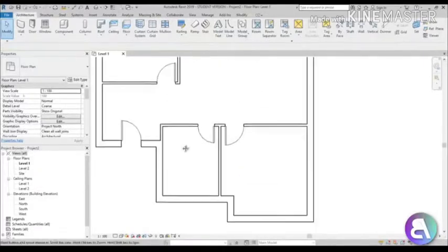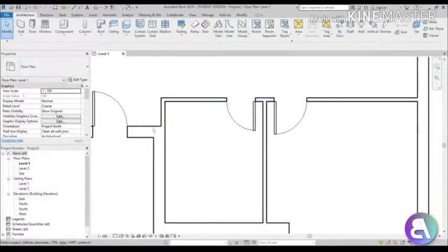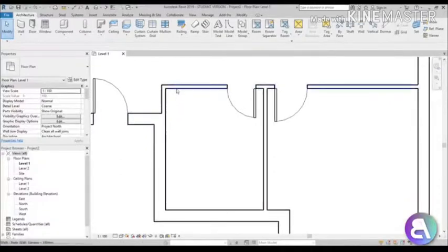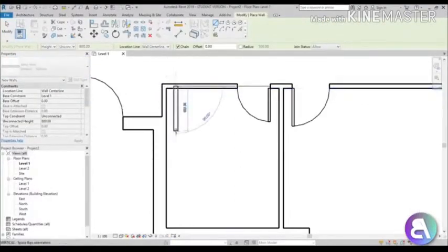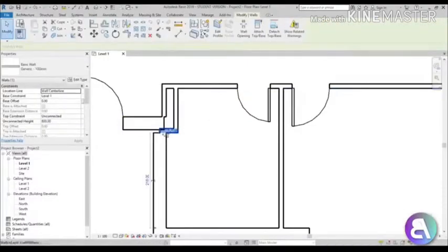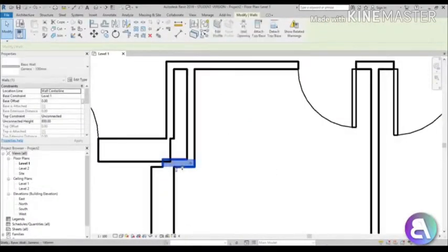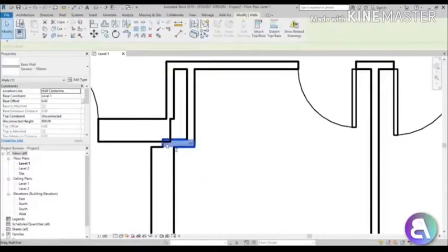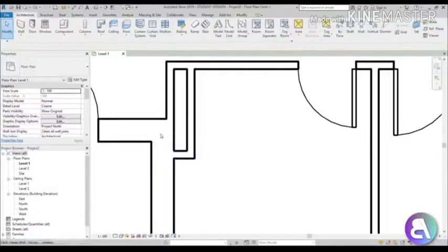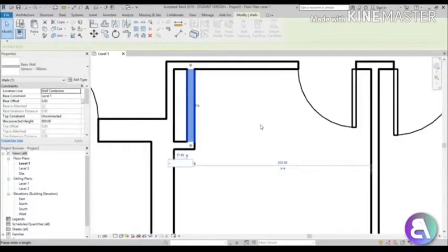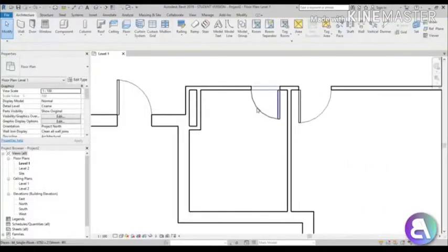Okay, so while we're here in the bathroom, here we're going to place the water closet. So let's make an area for all of the installations. Go to wall, choose 100 millimeter, and place something like this. And it might mess everything up, but don't worry, just undo. So you just detach this, and you just need to move it just a little bit, because it messes it up when you go to exactly this connection point. So you can place it like this and leave enough room, like 20 centimeters, for all of the installations that go over here.